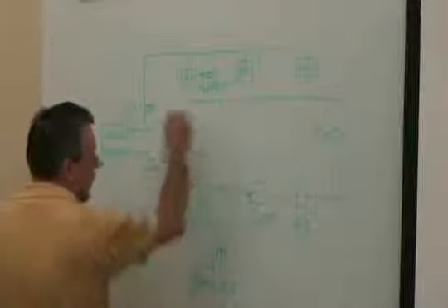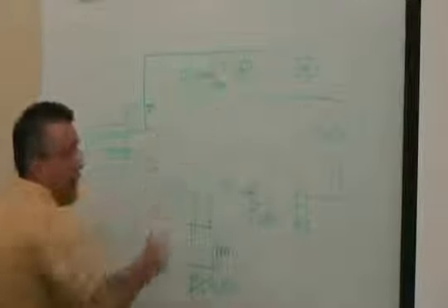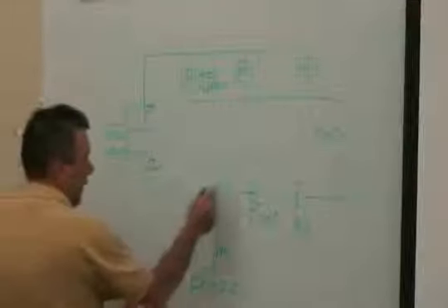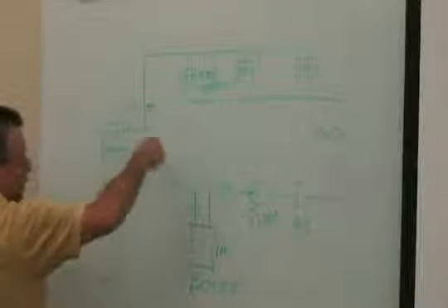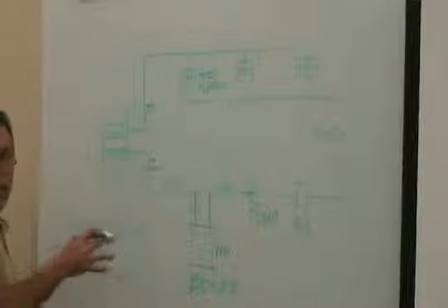So the range of my piping system is actually 100 to 60 degrees, depending on the time of year. If I'm full heating, everything's absorbing heat out of the loop for the compressor. So I'm going to operate somewhere in the seasons between 100 and 60 degrees. The loop will be operating in that temperature range.